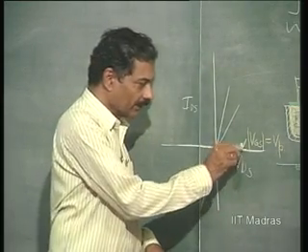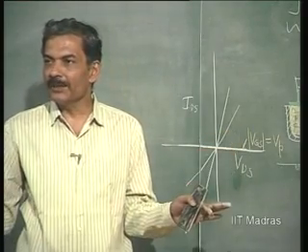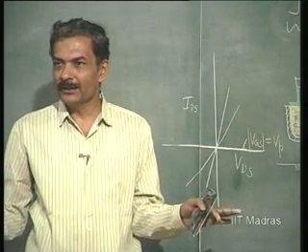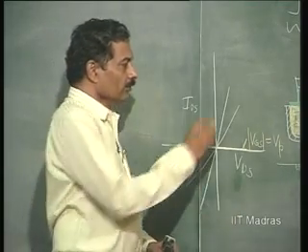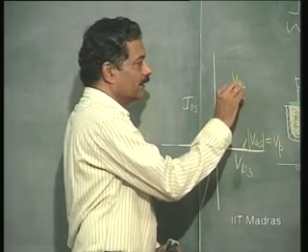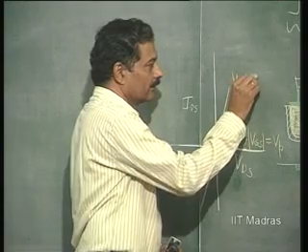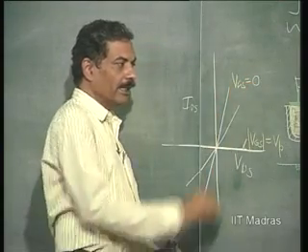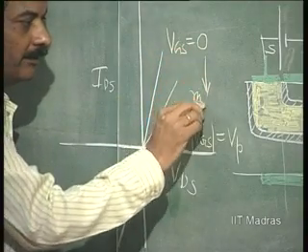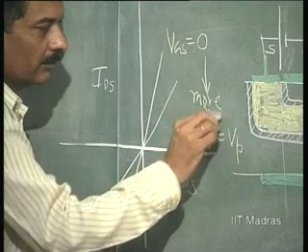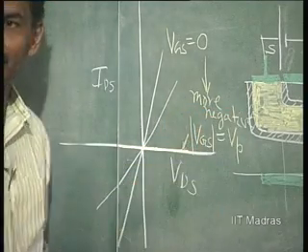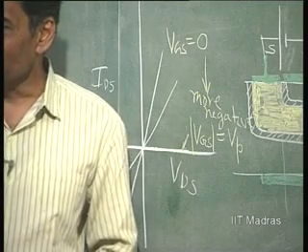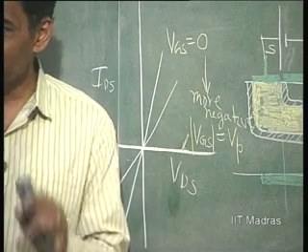This corresponds to that. There is therefore no connection between source and drain, and the current is 0. So, this is let us say VGS equal to 0 and VGS more negative, and ultimately magnitude of VGS being equal to some value called pinch off value. Okay, it is a negative value in this case.